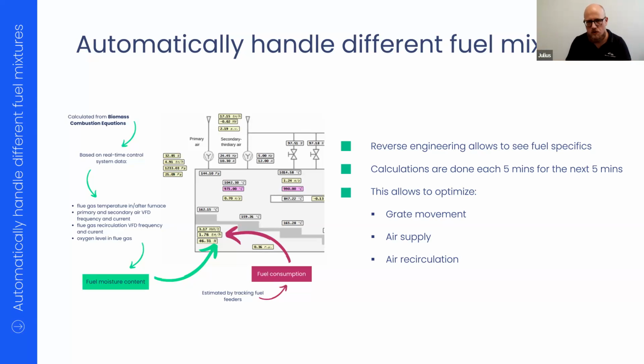In our case, we act as a doctor. We see that, for example, one of the fans has this kind of effect on the efficiency. Okay, that is good. Another zone doesn't have any kind of effect, etc. Then we find what is the most useful to use, and the control starts from there. Then you see that the efficiency goes up.